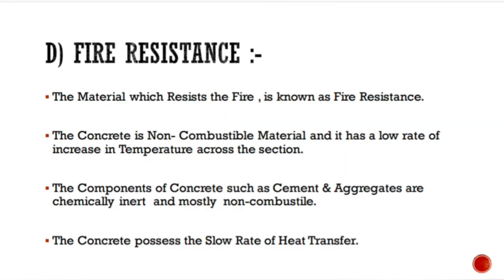Fourth, fire resistance. The material which resists fire is known as fire resistant. Concrete is a non-combustible material and it has a low rate of increase in temperature across the section. The components of concrete such as cement and aggregate are chemically inert and mostly non-combustible. Concrete possesses a slow rate of heat transfer.